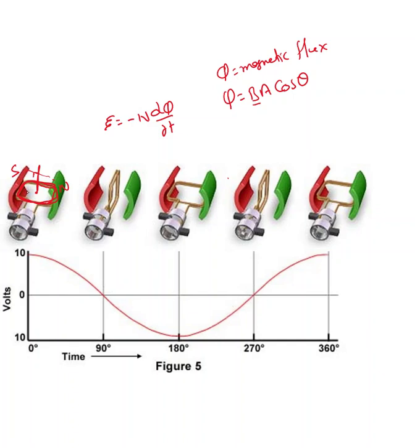In this case, what is the flux? Flux is zero. Induced EMF does not depend upon the flux; it depends upon the rate of change of magnetic flux. That's what we need to remember. So induced EMF, E equals minus N times d(BA cos theta) over dt.